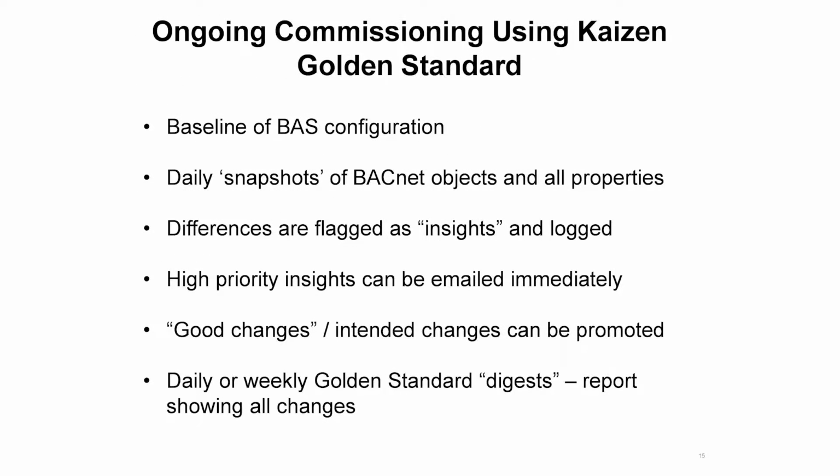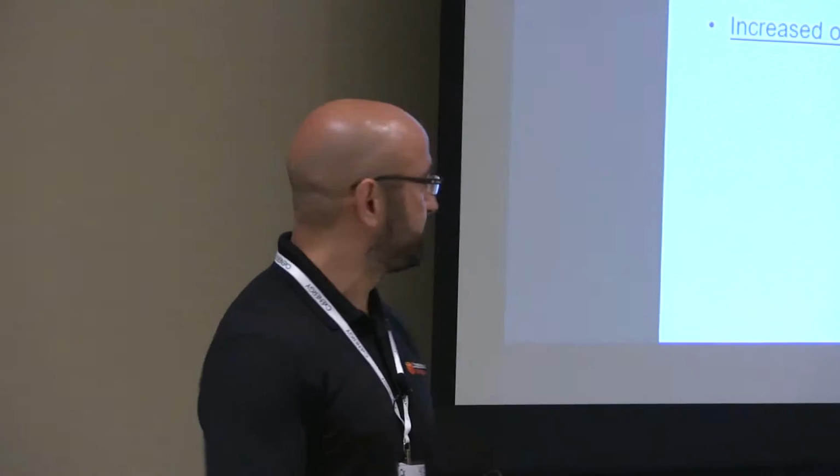So for that example, what you could do is set up a rule. One of those rule categories was sequence of optimization, right? So if you design the rule to look at a boiler system and say, this boiler system should be operating like this, and that could be per the ASHRAE design standard or just per how the building should have been set up to begin with, you get notified about situations like this without having an occupant complain or without having to investigate it in real time or reactively.